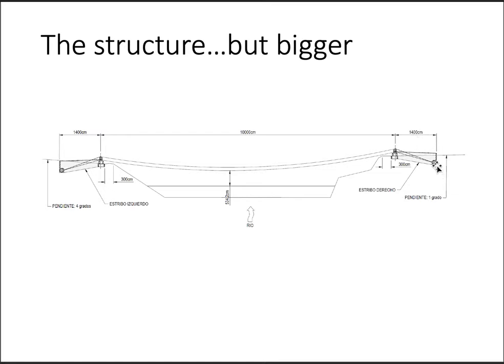And with the excavations, you're going to need to bench the excavations for safety reasons, and maybe you need to put some material here, or you need to walk behind here. So this is why we need 20 meters from edge of bank back as a minimum, really, because you've got to have a setback from the bank, you've got to actually have the whole structure, and then you're going to typically need a little bit of room back here. So this is why we need that.